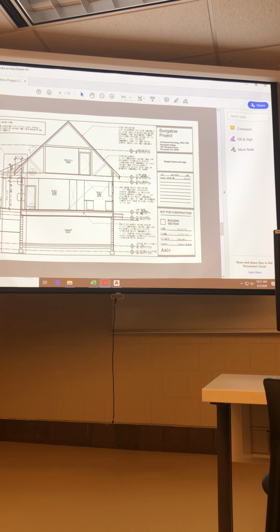Everybody see that? If I start from there, and start working up, my next datum elevation is where the trusses bear on the exterior wall that provide our roof structure and our second floor level. And the difference in height is we go from 100 feet to 109 feet, 1 1/8 inch, right? 9 foot 1 1/8 inch higher than my main floor level.